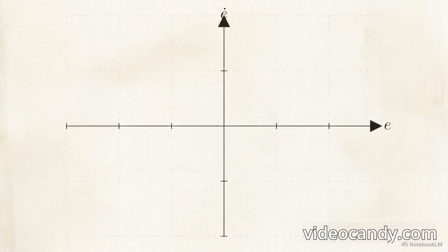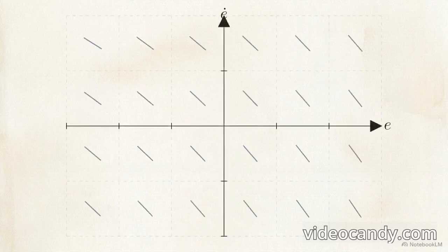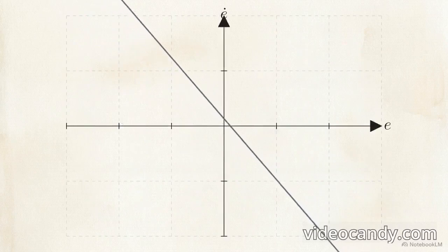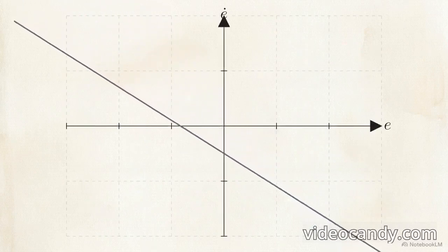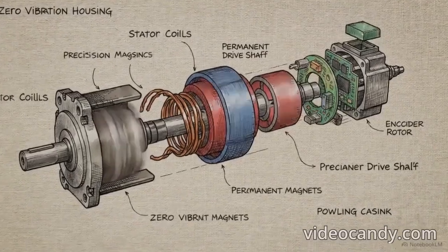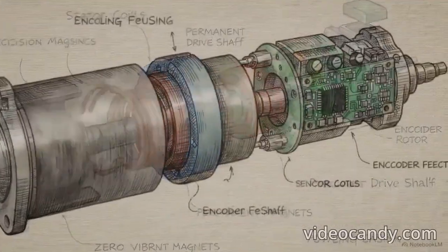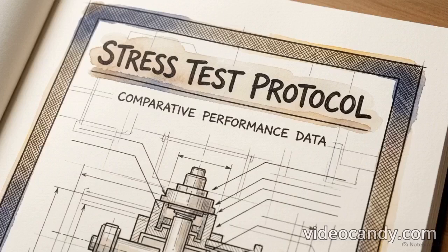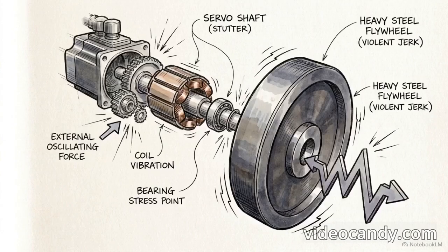This utilizes a Takagi-Sugeno fuzzy framework. Unlike standard models, the output of a Takagi-Sugeno rule is a crisp mathematical function rather than a fuzzy value. In this configuration, every fuzzy rule acts as an independent sliding mode controller localized to a specific part of the phase plane. This creates a moving switching surface. The line's slope and intercept adjust dynamically based on system position. To prevent chattering, a boundary layer surrounds the surface. Inside it, control action is interpolated, smoothly curving the trajectory toward the origin without high-frequency switching.